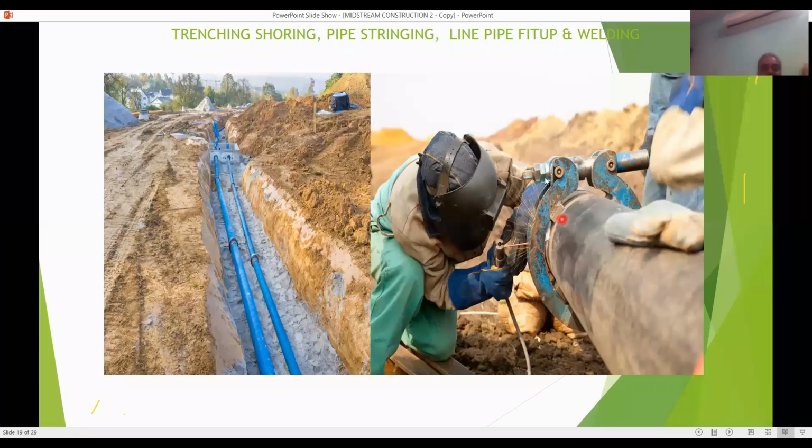See, this is a pipe spreader bar. This is called a spreader bar. A pipe should be lifted like this, because the pipe has plain ends and bevel ends, and these ends should not be damaged. If they are damaged, then your pipe length will be reduced.